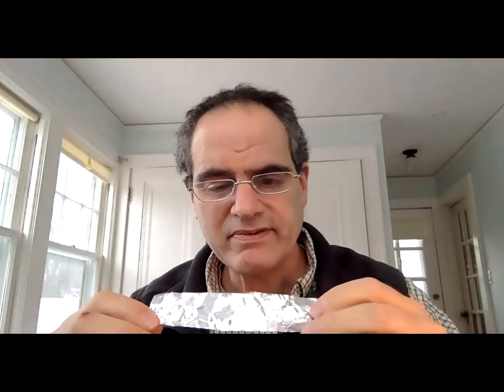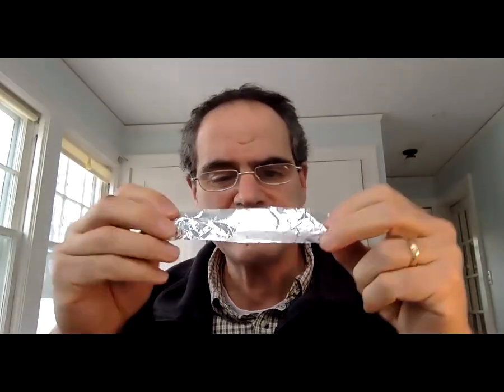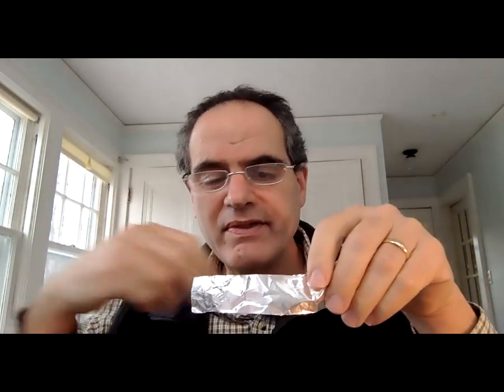Except that there's something odd about this. Aluminum also has the property that it's very reactive, and when it's exposed to air, it oxidizes almost instantly, forming an oxide that's a few tens of angstroms thick. The aluminum oxide is very tough. In fact, another name for aluminum oxide is sapphire. So it's a gem material, very tough and very insulating.